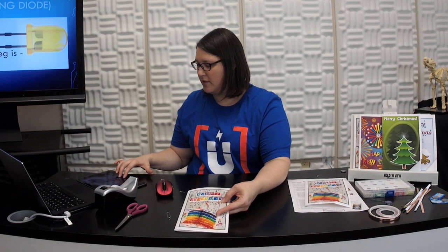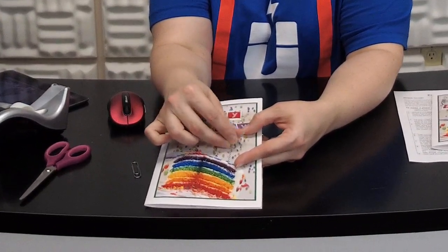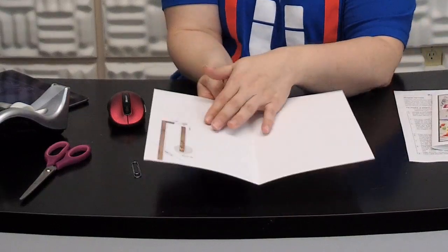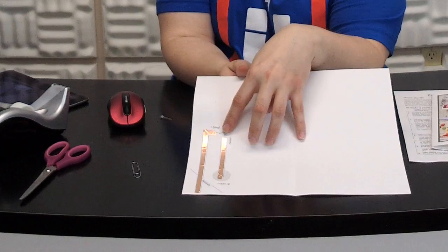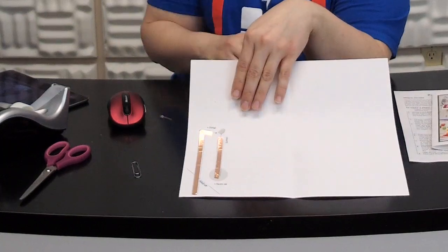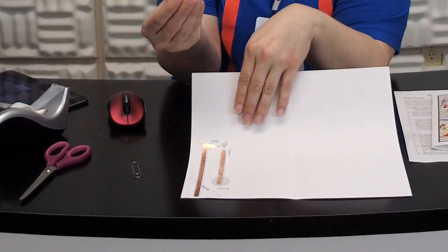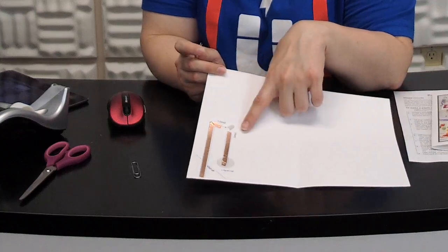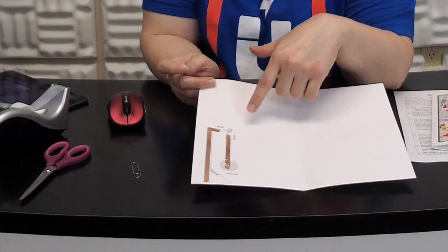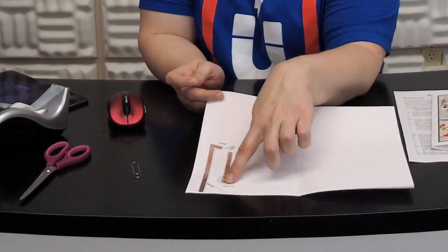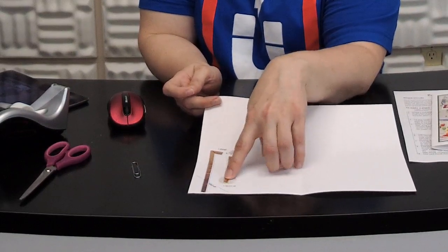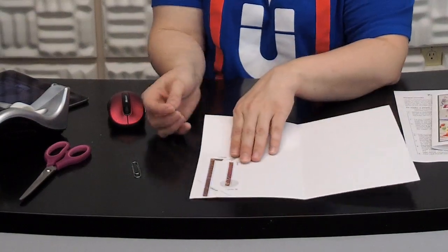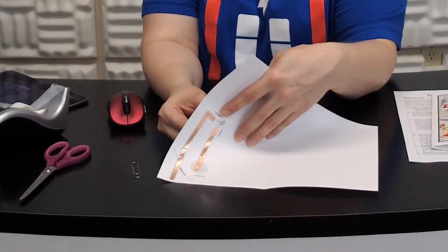So let me zoom in here so you can see what we're doing. So again, just put the thumbtack in, wiggled it around. Then I'm going to go to the back of my card and I'll be able to see the hole. I know you can't see the hole I've made, but I promise it's there. And I'm going to insert my LED lamp at this point. Now on our templates, we've written long and short to help you identify what goes where. But if you forget, you can always look and think, okay, bottom of the battery, and so that would be negative, so this would be positive, which means that our short leg, the negative leg, has to go over here. So I'm going to insert my LED light through the tiny little hole.